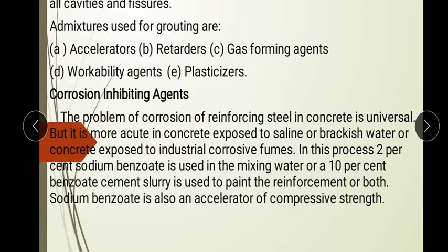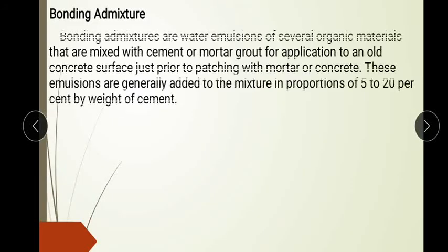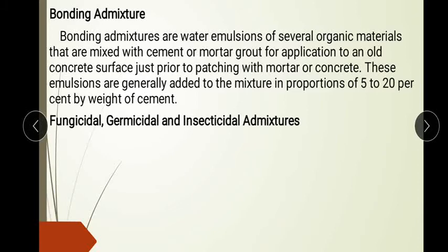They are constructing underwater structures, or structures which may be constructed in a marine environment. For that we use anti-corrosive, so corrosion-effective elements. Next one, bonding admixtures. These are generally added for grouting, where we require more addition to the cracks. So for that we are using the bonding admixture.